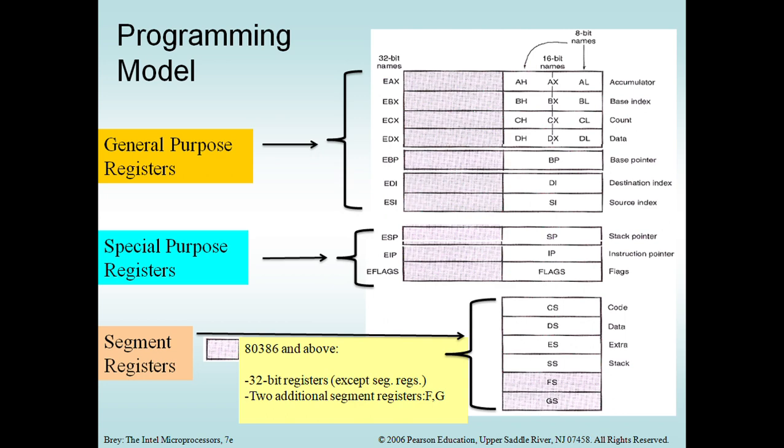For high-level languages such as Java, C++, it is not that important to understand the detail of the registers available in that microprocessor. But for low-level languages such as machine language or assembly language, it is important for the programmer to know the uses, names, and sizes of available registers, or in other words, program visible registers. These are registers that the programmer can use while developing applications in assembly language.